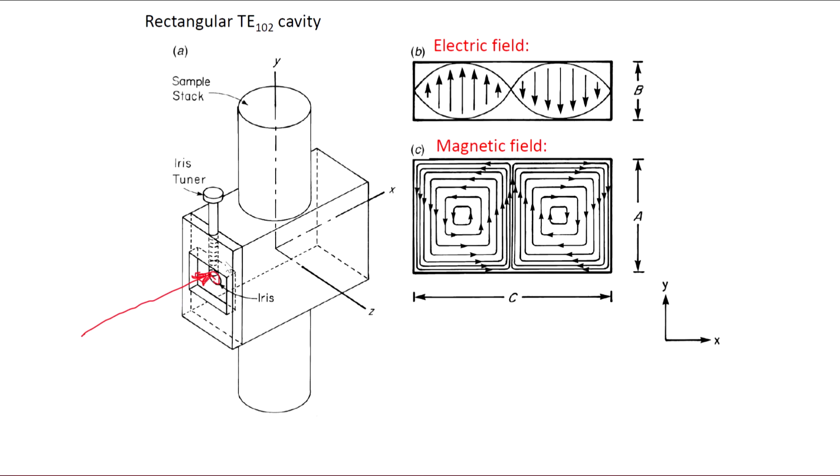couple it. The reason why is that if you look at the cross section, this is how the electric field looks like in the cavity. So the electric field comes in this way, and then there is a standing wave in there. This is the standing wave, and you have to control this entrance of microwaves to get good standing waves in there, and you control it with this screw. So basically you have a screw that you can move up and down, and that allows you to get more or less microwaves to come in and form the standing wave.